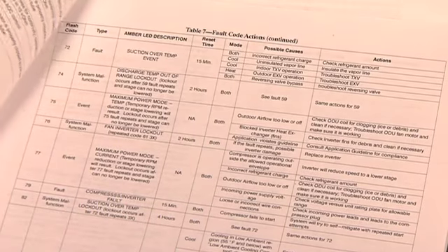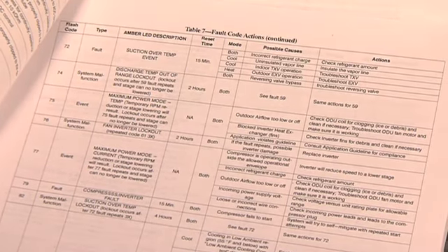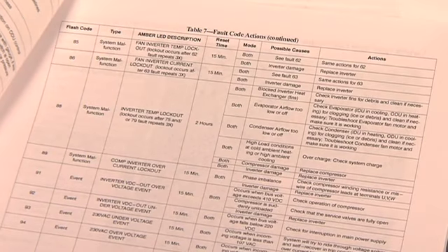Now let's talk about when to use a multimeter. There is no reason to use a multimeter to check inverter output to the compressor or fan motor. That's because there is no published value of voltages versus the compressor or fan motor RPM. If the compressor and fan motor will not operate, use the fault codes to diagnose the possible reason. If the compressor and fan motor will operate, the inverter output is good.